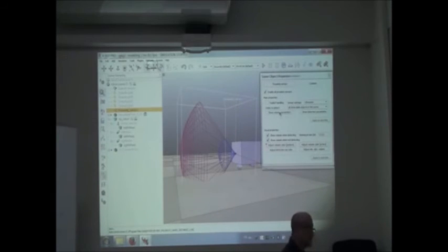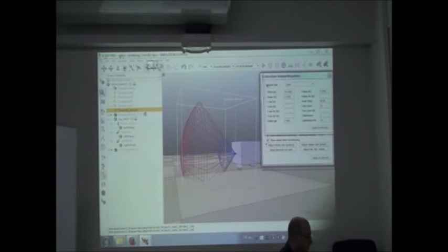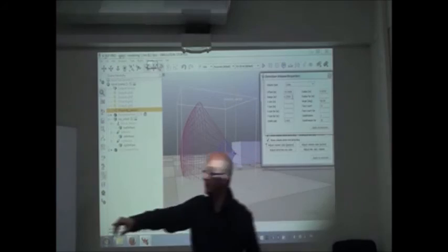Okay, now we need to change the volume parameter, we want to change the shape of the volume. So, show volume parameters. And here you have volume type. Offset, that would be from where we start to measure. 0. Range, 30 centimeters. I put there the range I want based on the hardware I bought.